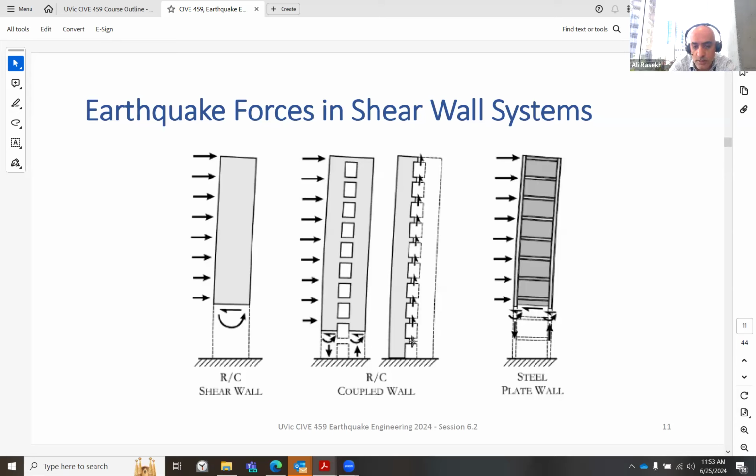Also the shear at these narrow pseudo beams would go high because the left portion and the right portion, in a way, are interacting with each other through shear in the middle. There would be a bigger than usual shear force in these short beams.